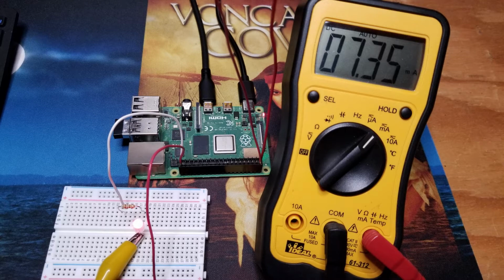And that will also change from resistor to resistor of the same value. Some will measure high, some will measure low. They're usually not dead on. That's why they have a tolerance rating. Now the diode, we use a 2-volt diode drop, which is the typical value. But the table also showed that it could go up as high as 2.6 volts. So that will vary a little bit as well from diode to diode. So basically we're using an approximation to determine our value. And you can see we're pretty close. We're 7.35 versus 7.2, so we're not really too far off.